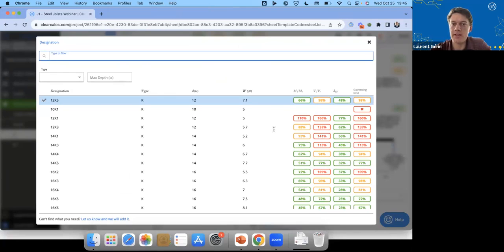And Pete asked, is the 9-foot measured to the center of the unit? Pete, you're right. I took a couple shortcuts here. I just called it 9 foot. Typically, say for your snowdrift, you might accommodate for that. Or if you had, say, 2 legs for your units, you might split the weight between the 2 legs and put them in as individual point loads. Again, I took a couple shortcuts here. I'll own that part. But that was just for the example.